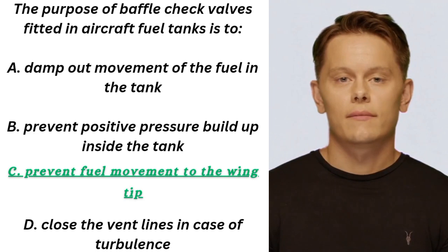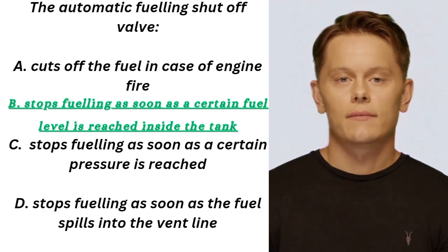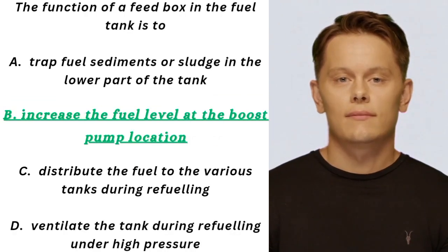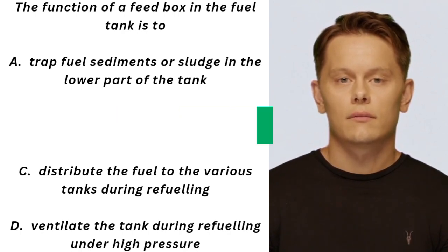Question 28. The purpose of baffle check valves fitted in aircraft fuel tanks is to. The answer is C. Prevent fuel movement to the wing tip. Question 29. The automatic fueling shut-off valve. The answer is B. Stops fueling as soon as a certain fuel level is reached inside the tank. Question 30. The function of a feed box in the fuel tank is to. The answer is B. Increase the fuel level at the boost pump location.